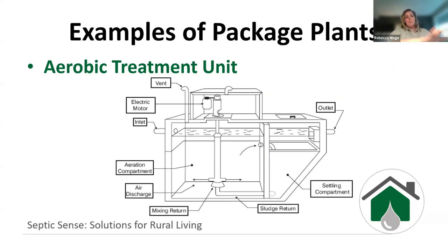Upstream of this, before we get to this treatment unit, we have to have a trash tank, because not everything's supposed to be flushed. And if it's not supposed to be flushed, it can't make its way in here by accident. So before we can install this, we have a trash tank upstream from this.